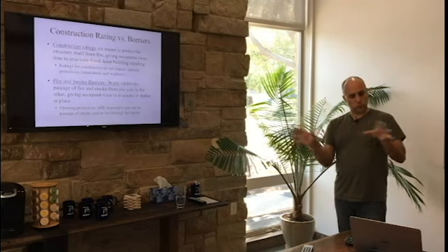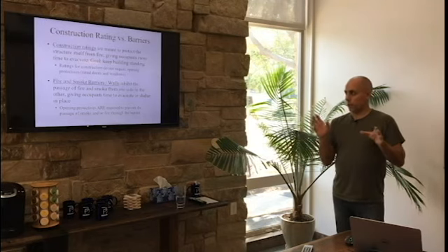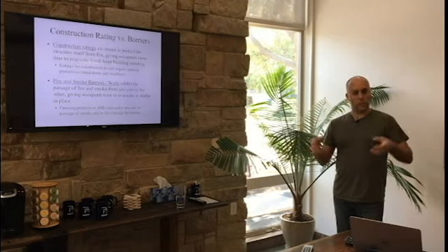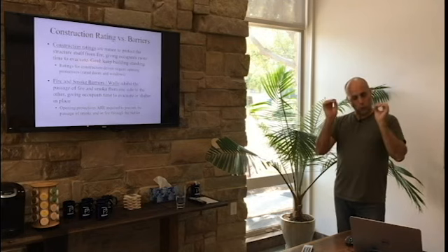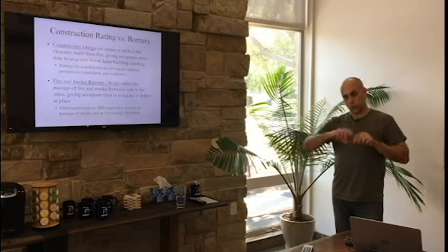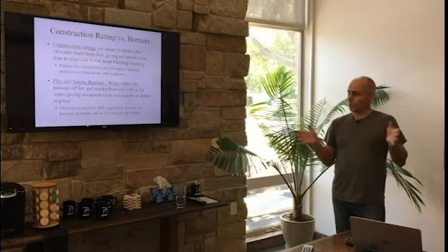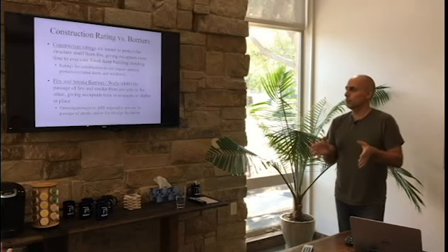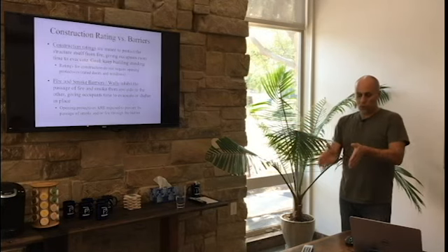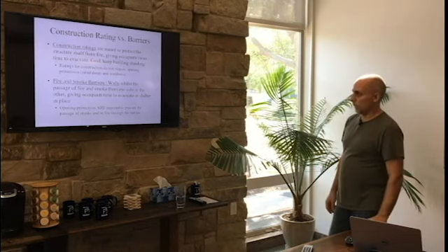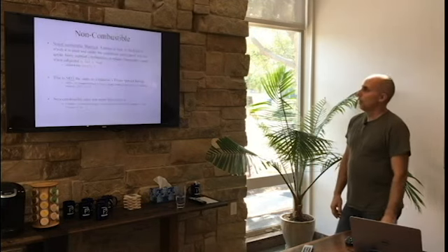This is educational, so it's different than healthcare. So we called out 45-minute doors. The contractors were freaking out because they thought they needed 3-hour doors in a 3-hour wall. It's like, no, the 3 hours is the construction rating, which 7 1/4 inches of solid concrete provides us 3 hours of construction. It's not going to burn down in less than 3 hours. But we only need an hour of separation. So it's two different reasons for having a rating on a wall.